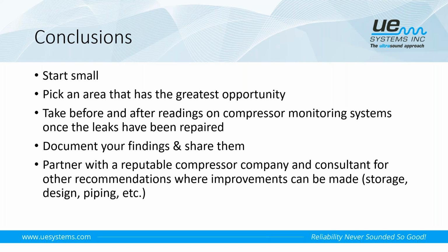Take your before and after readings on your compressor monitoring system. If you have a way to monitor, let's say, the amp draw on your compressors before the leak survey and then after the leaks have been repaired, I guarantee you'll see a decrease in amp usage, simply because the compressor is not working as hard. Document your findings.